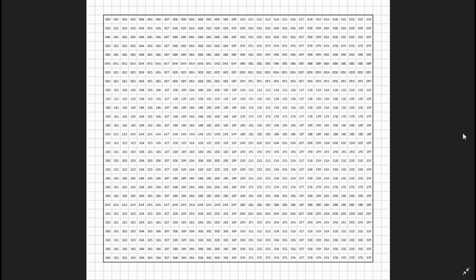So the screen memory is laid out. If we're looking at the TV as it's normally placed, it will start top left and do a raster scan from top left, right, and then down, and it goes from memory 000 up to 01F, and then every line, so that's 32 squares, and it will go down until it reaches 37F. And in actual fact, the chip that we are going to use for this will go to 3FF, which will be 400 hex, effectively, in terms of the space.